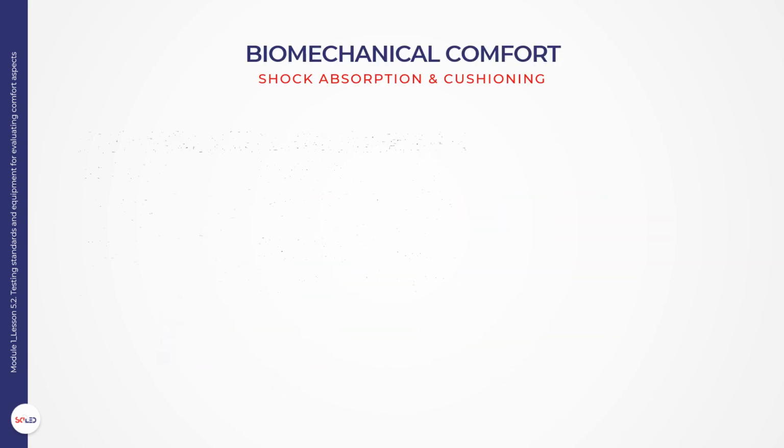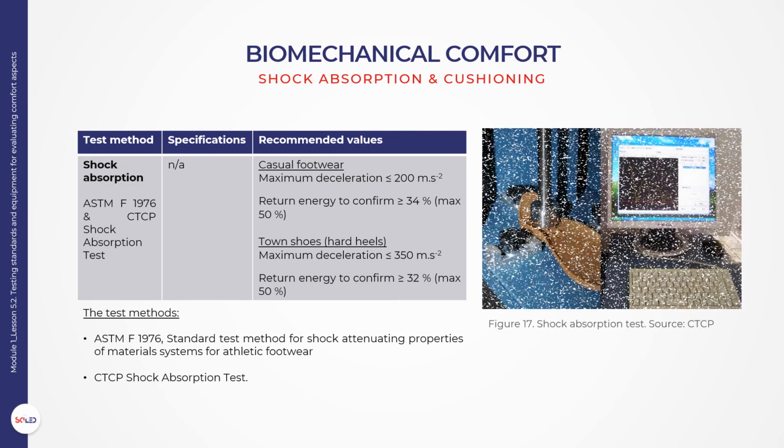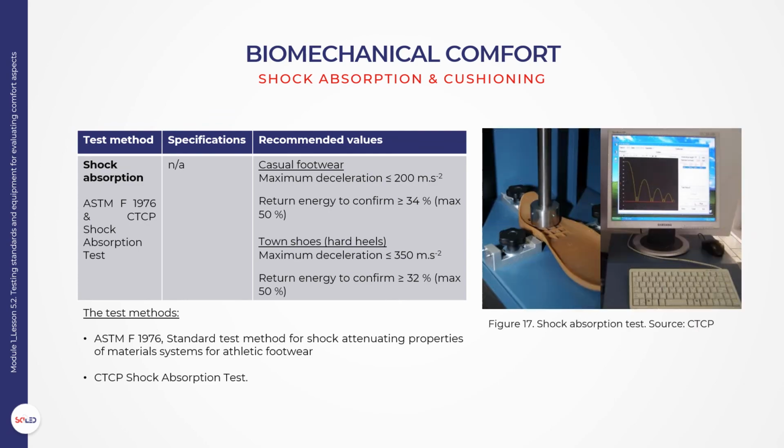Shock absorption. Shock absorption is related with the absorption of impact forces, mainly on heel, during the walking. The shock absorption will reduce the potential harmful impact forces that occur during running, jumping and walking, among other activities. The recommended values for casual footwear are: maximum deceleration less than or equal to 200 meters per squared second. Return energy greater than or equal to 34%, maximum of 50%.